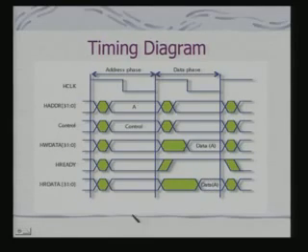Now, this timing diagram is very similar to what we have seen in the context of a simple memory interfacing. But the overall transaction definition with respect to the bus, which involves communication with the arbiter and grant signals, as well as the response signals coming from the slaves, makes the transaction much more complex than that of accessing a simple memory.